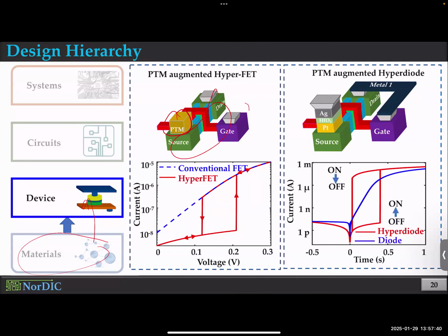But remember, a device cannot work alone. You must have seen the architecture of memory. You need decoder, encoder, sense amplifier. You'll not use a sense amplifier for just one cell. That's completely impractical, right? You'll have an array of cells, rows and columns. How many of you remember the discussion? We use one decoder to choose the row, one decoder to choose the column. So if you have just one cell, you cannot do anything with it. As long as you're just dealing with one cell, you are dealing with the device, but you still have to go to the next level to do anything practical.